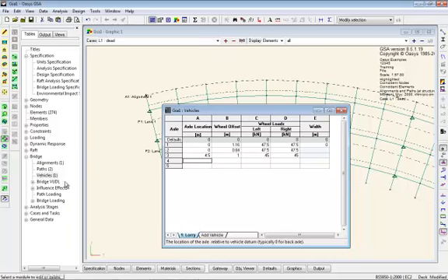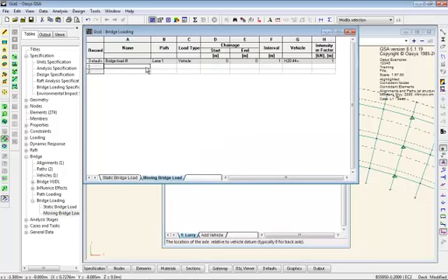We then need to apply this to the bridge. Now I'm going to create a moving bridge load, and I am going to put it onto lane 1. Vehicles or knife edge loads. Take a vehicle, starts from chainage 0, ends at chainage 90, and we're going to put it having 1 meter steps.